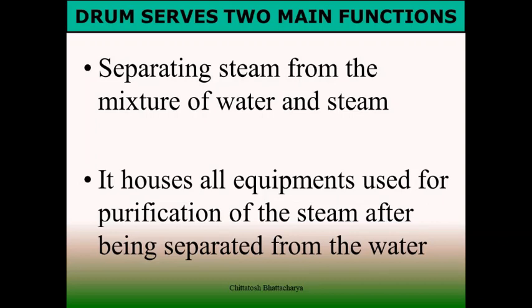Besides separating steam from the mixture of water and steam, the drum also serves the purpose of purification and drying of steam. By drying, actually we mean removal of moisture so that only saturated dry steam comes out of the boiler drum and goes for superheating.